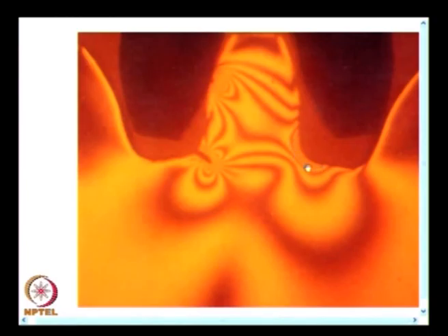And suppose for example, I need to measure strain on this fillet, you could see there are many fringes densely packed in this corner. So, that indicates obviously you have a stress concentration zone, and if I have to measure strain in those locations, I can't use the general purpose strain gauge of length 3 millimeter. I need to use a strain gauge smaller than that.